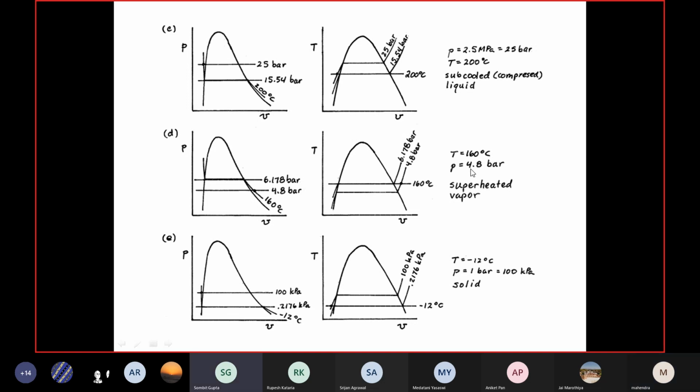It is not given directly, so I was doing linear interpolation. It came to somewhere around 150.3. Otherwise 4.75 or 5 would have been given. Yes, 4.5 and 5 are given. At 4.5 it is 147.9, and at 5 it is 151.9. Even at 5 bar itself it is about 151, as we have seen earlier.